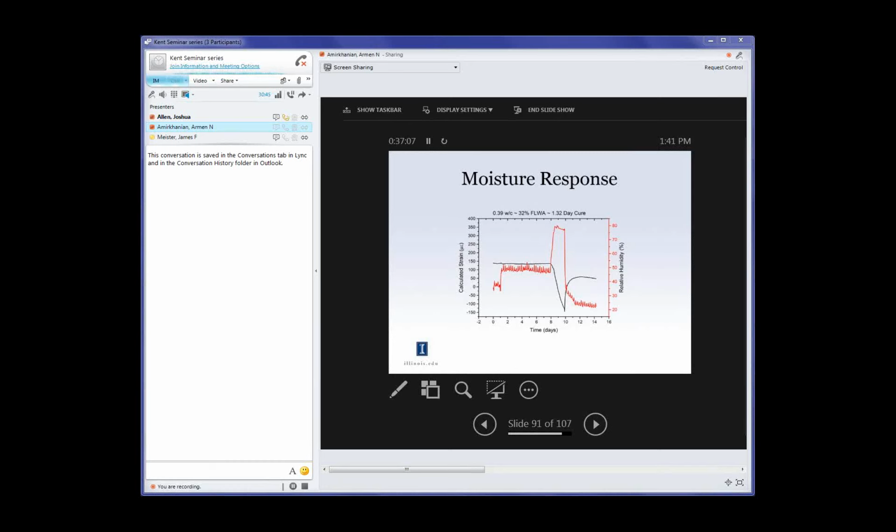This actually went back the other way because we've now entered a negative curling strain. So it's actually going back the other way from 0. And 0 was just calculated from the start of the test. So that was quite fascinating to see as well. And this is, again, only a humidity change. We're going to look more into this. This was done like last week, so we don't have much more analysis. And these spikes right here are the defrost cycle as well. So it was interesting that we came up with this and saw this behavior.